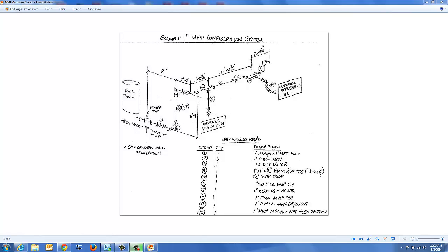At the top of the wall we're going to have another elbow, and then a third elbow that will penetrate the wall. This kind of a can denotes that wall penetration. We're then going to put a T in here, a female by male by male T that also has a drop on it, item 5.